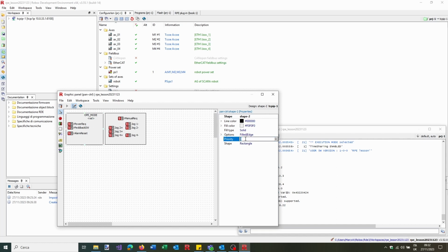So I go here on the shape and I can modify the priority. Now the priority is 0. I can say -1, so it will go behind. Now I can click and touch things because they have a priority 0. If you make a higher priority, you will make them go to front. Here again, we say priority -1, so they go all behind, and now here we can touch the buttons.